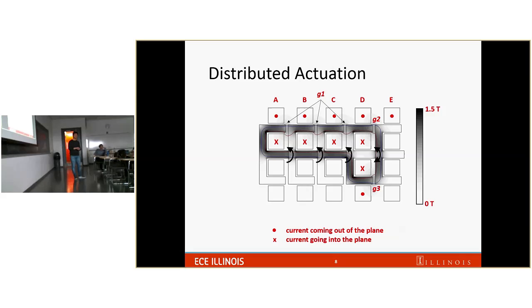But keeping a neutral position is impossible, I think, without current, because there's an air gap in this system now, so whatever the whole system moves, it'll fly away. So the current should be excited to firm that position. I mean, you're saying if you put springs there, then you maybe wouldn't need to use current to maintain, or at least use less, so that your current use would just be to correct differences from the neutral position instead of maintaining it all the time.